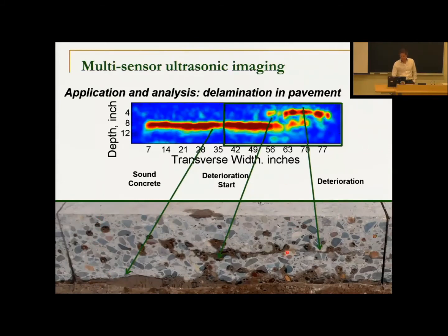But to the right-hand side, we have a nearby defect, right? So this gives us this cross-section, that representation that we see here. It's a very effective way to tell us what's going on inside. These kinds of multi-array ultrasonics give an image which represents, in most cases, a cross-section that shows the position of any sound reflectors. And we know that wave reflectors are usually interfaces with very different impedance. That means air-filled holes or air-filled cracks.